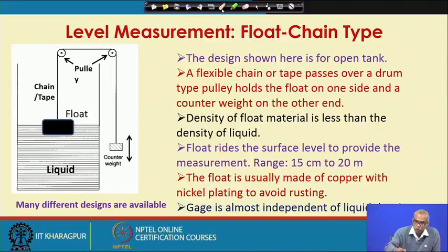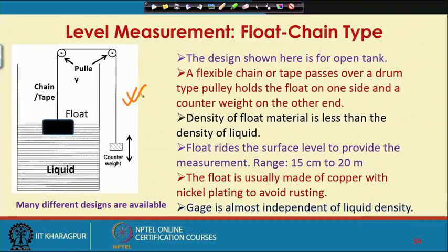The design that is shown here is for open tank. A flexible chain or tape passes over a drum type pulley, holds the float on one end and a counterweight on the other end.